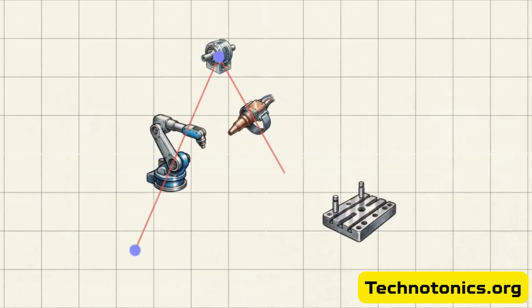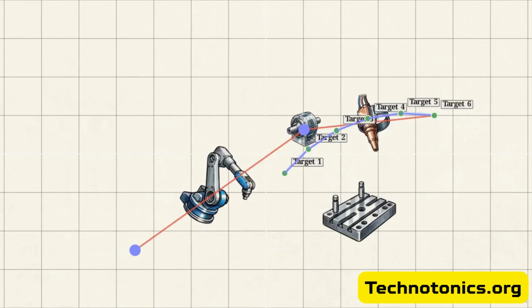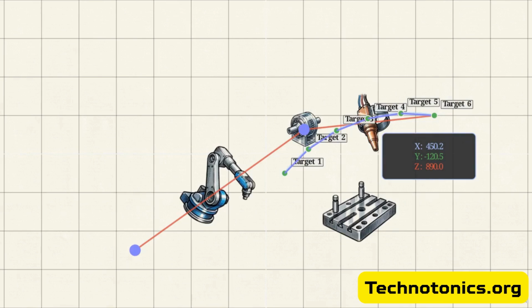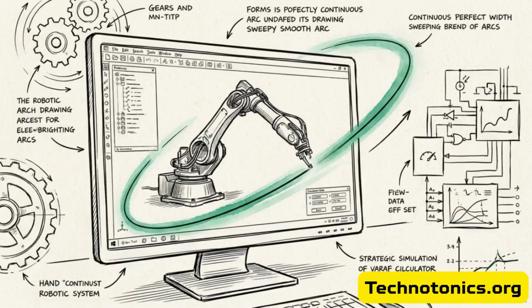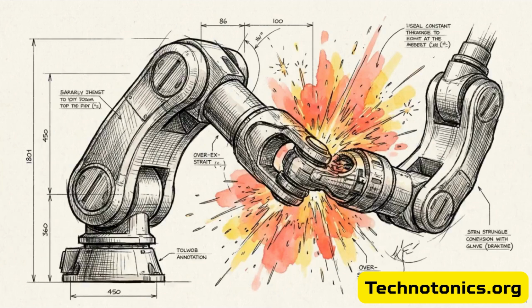Layer 2 applies accurate kinematics, where offline programming begins, translating theoretical design into robotic movement. Path generation is dictated by process parameters. We input weld tolerances, turning a continuous curve into a strict sequence of numerical targets. A generated path might look perfectly efficient on a screen, but that does not guarantee the mechanical joints of the real robot can physically achieve it without hyperextending.